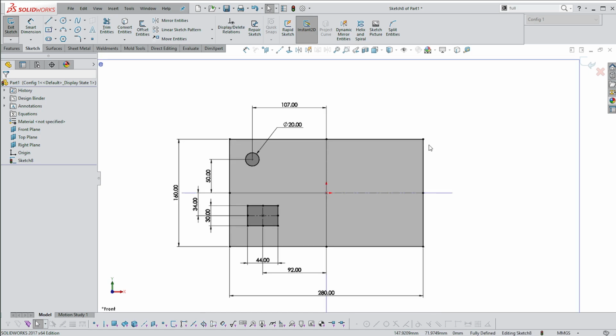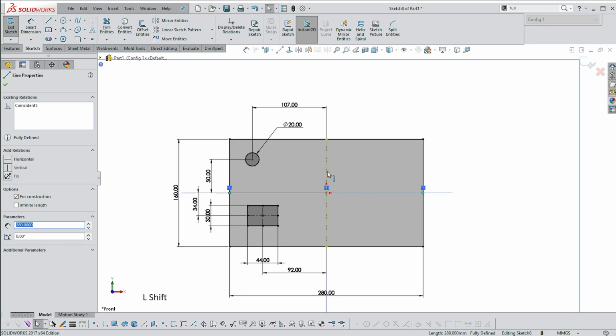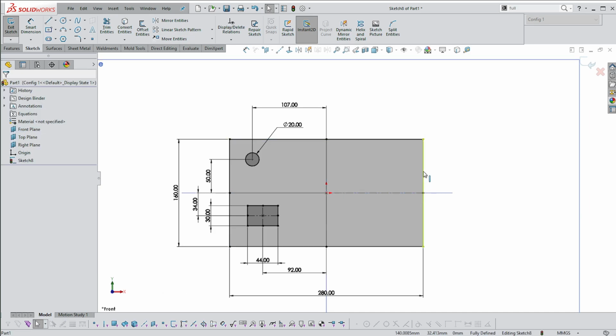All right, just one more thing, maybe. Have a look at this rectangle, the main rectangle. You might say, well, okay, it's fully defined. What position does it have? Well, it has a position of 0, 0. So it starts from 0, and we know that each one of these lines is centered on either the verticals or the horizontals. So we know that this is positioned around the 0, 0 at a distance of 140 to either side, left to right, and of 80 top to bottom. So many size positions are implied, and you'll get to understand that better as we go along.